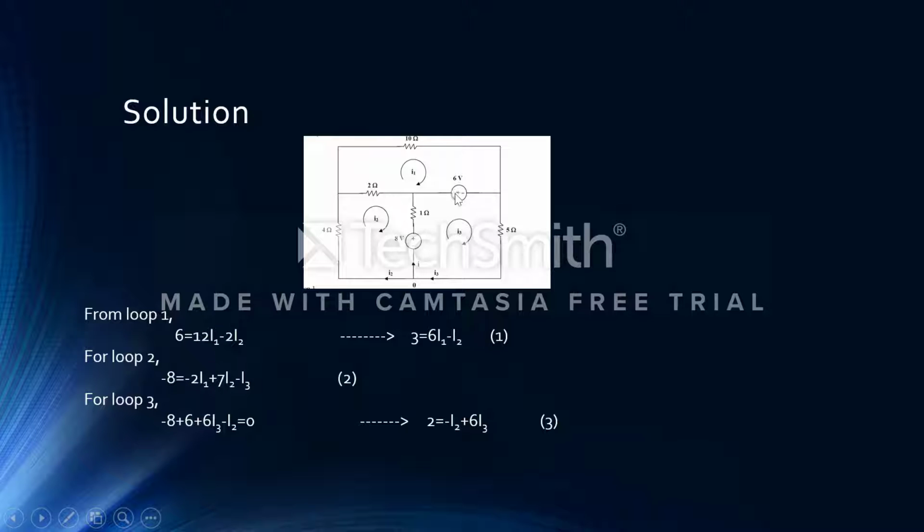Going through here, 6 is equal to 12 times I1. That 12 times I1 is nothing but 2 times I1 minus 2 times I2. So we are adding up this 2 times I1 and 10 times I1, and we are getting 12 times I1. And the same I2 current flows over here, but in the opposite direction of I1. So we include a negative sign for that. So on simplifying that equation, we get 3 is equal to 6I1 minus I2. This is our equation 1.